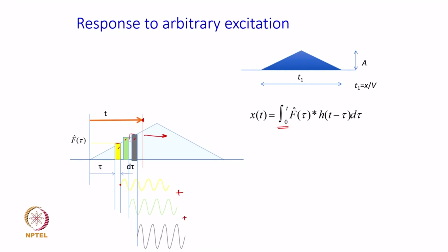Okay, the blast loading which we mentioned in our introductory part has an amplitude equal to a, which happens after reaching a time t1 by 2 from the start. So, our time starts at this point because there is no loading before that, so the whole tank is stationary as such. The blast happens for a total time of t1, and it reaches its peak value in t1 by 2 and then subsides in the remaining t1 by 2. So, if that is the case, how do I evaluate this?